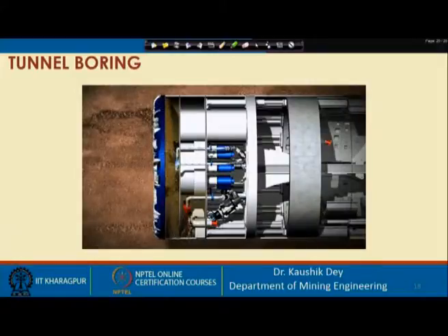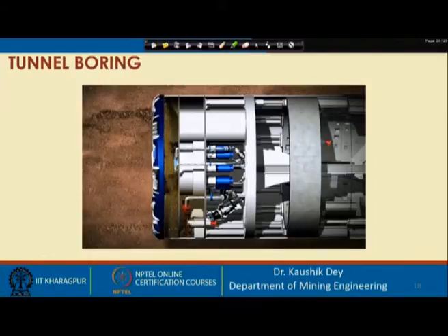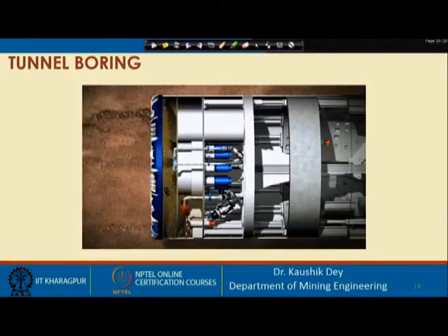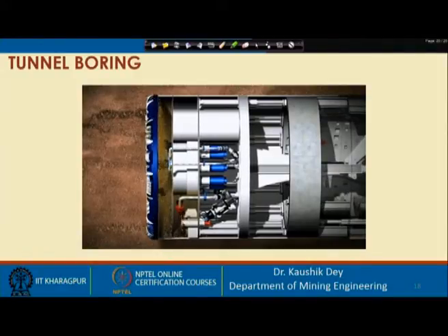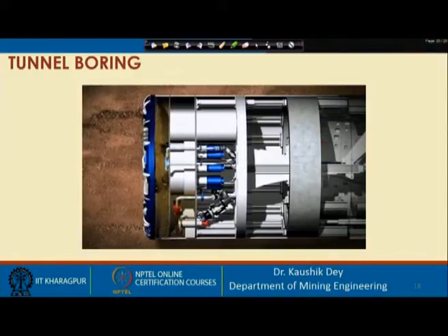The excavation chamber is behind the cutting wheel and is separated by a submerged wall from the working chamber. In this case, the excavation chamber is completely filled with bentonite slurry, and the working chamber is approximately two-thirds filled. The two chambers are connected through openings in the submerged wall, communicating via pipes. The transportation system is the material being pumped out, not a screw conveyor system.